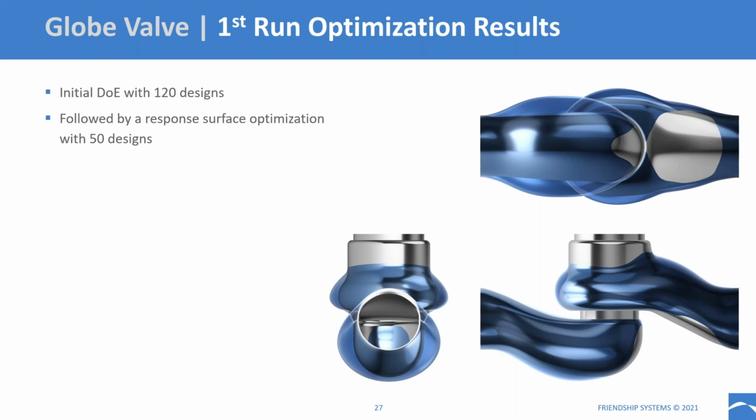And then on this response surface, we can run an optimization. The results for the optimization process are taken from the surrogate model, but every now and then we run a CFD computation again to double check our results from the surrogate and see how accurate they are. Then we take in those results to refine our surrogate model, until we are converged up to a certain optimum within the design space. That ran with another 50 designs that were computed by CFD.